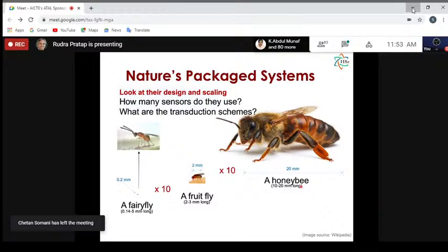Triggering an event that, hey, if you sense a shock of 500G, then do this, right? So if 500G is the acceleration that this sensor here senses, then it latches here and it completes the switch, which could trigger another action.